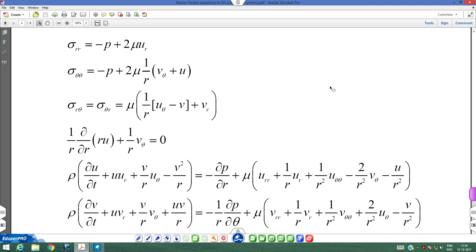I mentioned last time that if you work in coordinate free form, then those very special forms of acceleration such as centrifugal and Coriolis will automatically emerge. You do not have to add them separately. So, it is a unified formulation of the governing equations. And where will you find the acceleration terms? On the left hand side with the inertia terms, mass times acceleration. That is where you will have acceleration defined in a curvilinear coordinate system. Terms such as u v divided by r, v square over r.